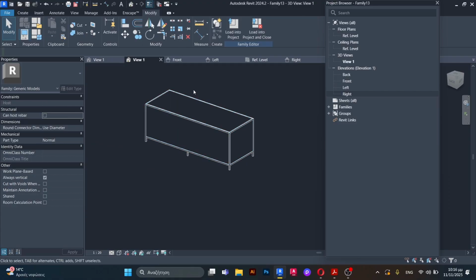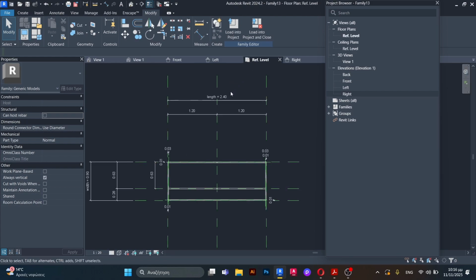Perfect. Now it's time to define where the kitchen fixtures will be located. Again, reference level. We will have 55 centimeter length for the sink, 60 for the dishwasher, and also 60 for the induction hob, while another 60 centimeters will remain as an open space. Once we have defined all the stuff, we will create the voids for our kitchen cabinets.